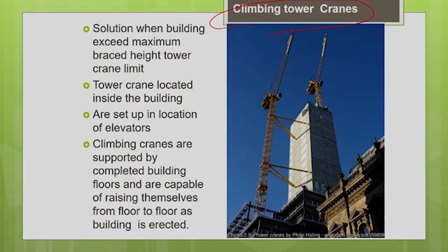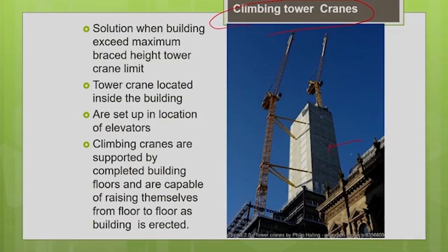Then, as a few floors are completed, you detach this tower crane from the foundation of the structure, and then shift it onto the desired floor level and attach it with special collars to that particular floor. Okay. So, that is why when you design this structure, you should know that it has to support the crane and the load from the crane also. That has to be taken into the structural design of the structure.